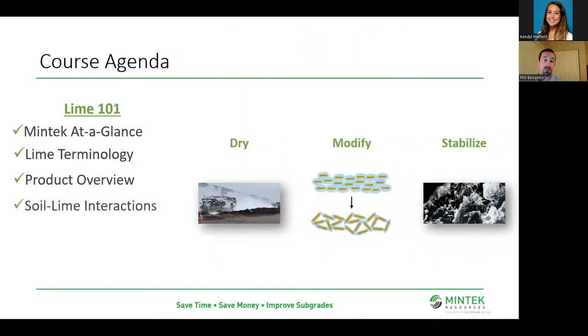And then we went into the soil interactions. We're going to dry it. We're going to combine with the water that might be present in those wet, soupy messes, those sites that we're often on. Also going to force off additional moisture in the form of steam. On the modification side, edge to face or edge to edge orientation of those clay particles, rearranging to the edge to face, basically making an engineered fill material. And then soil stabilization, where we're really pulling on those pozzolanic bonds that we're forming when we introduce our products to the soil.